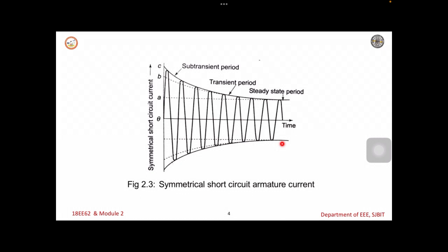When the rotor rotates, the armature winding is cut by the magnetic flux of the field winding. Here the three phase alternating EMFs are induced in the armature winding. In turn, alternating three phase currents are set up in these windings, and this produces a rotating magnetic field which rotates at synchronous speed in the air gap.